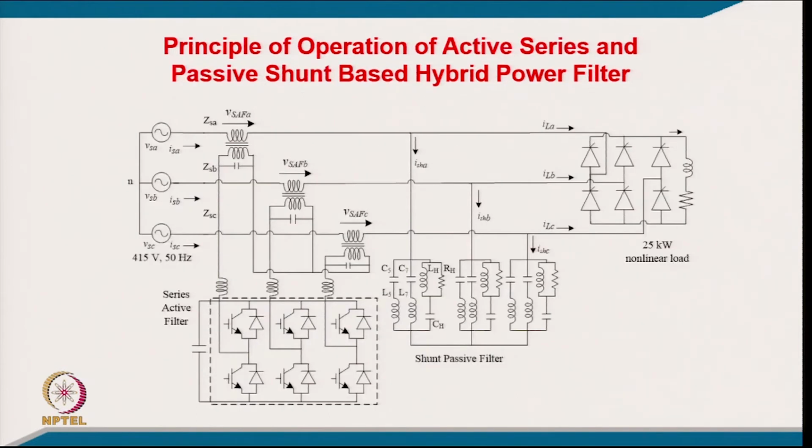And this is another quite popular topology, where you have a current fed kind of load: a thyristor converter, maybe an RL load, it may be a DC drive, or it can be a current source for your large rating synchronous motor drive. There are plenty of loads of such nature. So, a major amount you are putting like a passive filter here, and you are not disturbing the current fed kind of load because you are connecting in shunt.